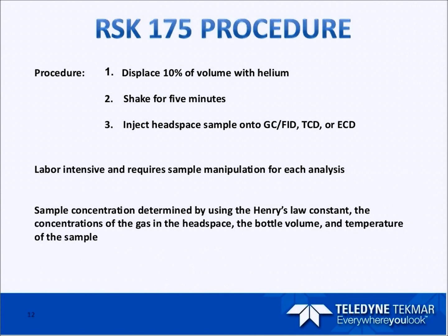Actually, the response you get is back calculated, and this is a lot of the actual SOP, is the calculations on how you get your gas concentrations based on your response on your GC. But it takes into account the headspace, the volume, the temperature, to determine what the actual end concentration is. But this is all done by hand. It's all manual.